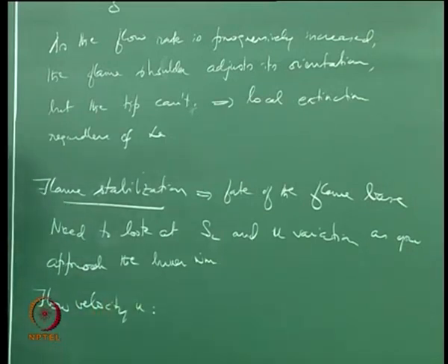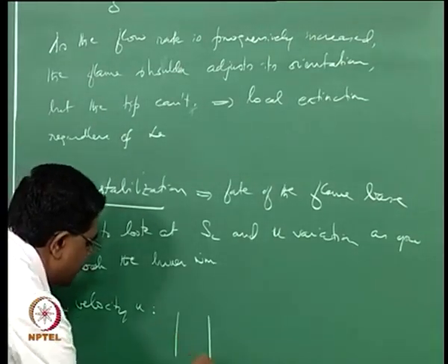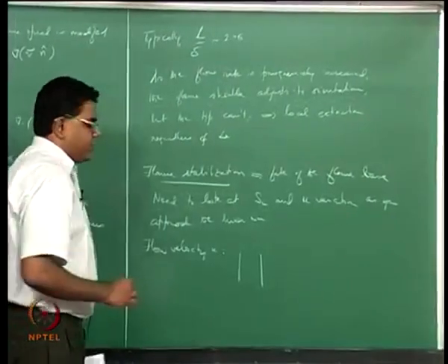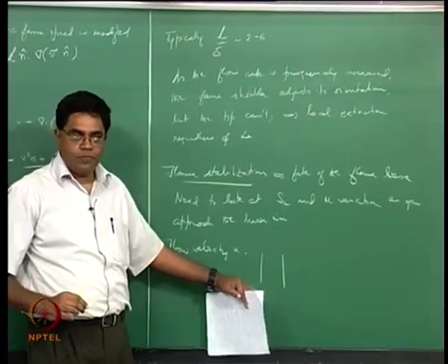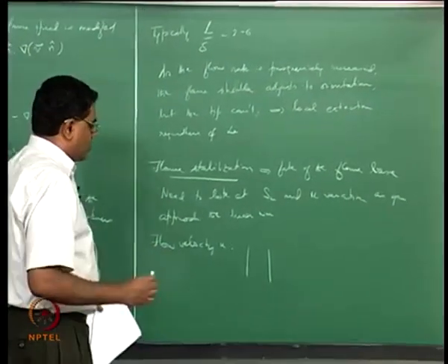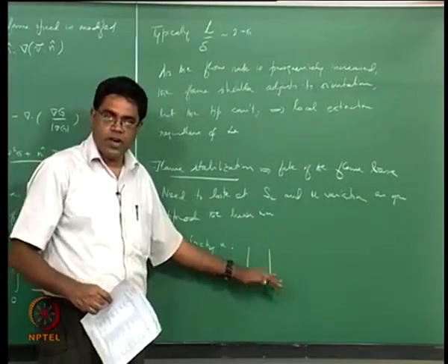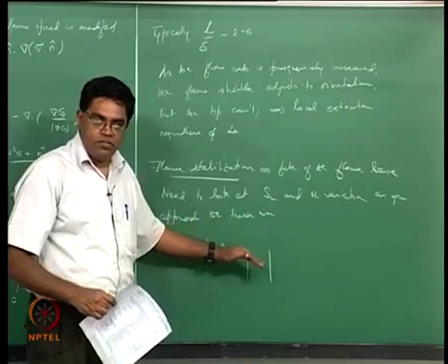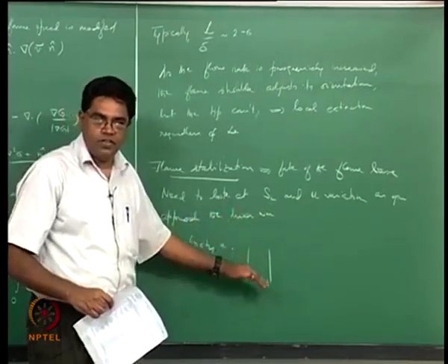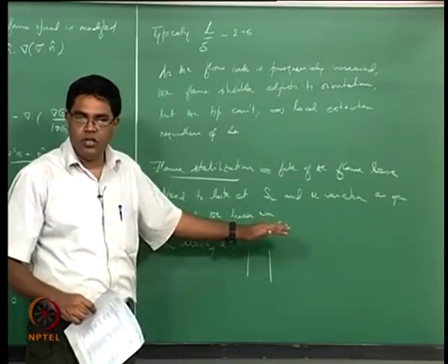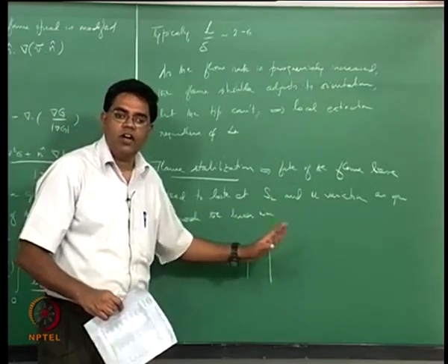So what we expect is if you now have a burner, we have a no slip boundary condition. And of course you could quibble saying we don't know exactly how the flow was formed and where and how it is developing, as it reached a fully developed profile, do we have an entrance length associated with it and so on. Those things are not very relevant.